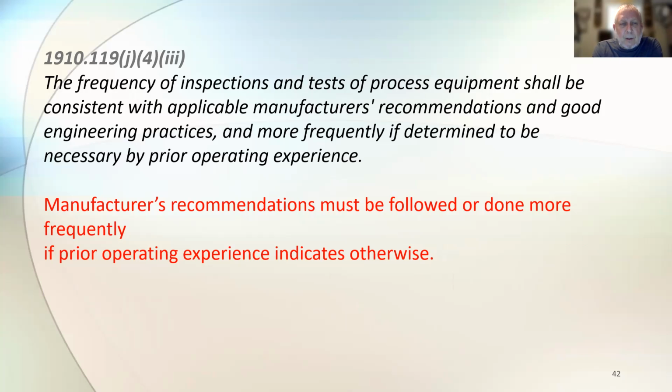So basically, the manufacturer's information you get when you buy something is as good as law, basically, because it's quoted in here. And one of the things we did with our emergency relief valves, there's always concern about whether they're going to function. So we took five of them that were 5 years old, because that was the manufacturer's recommended interval to change them, every 5 years. We sent them out to be tested, and they all functioned properly. So we were pretty confident that the 5-year interval was acceptable.